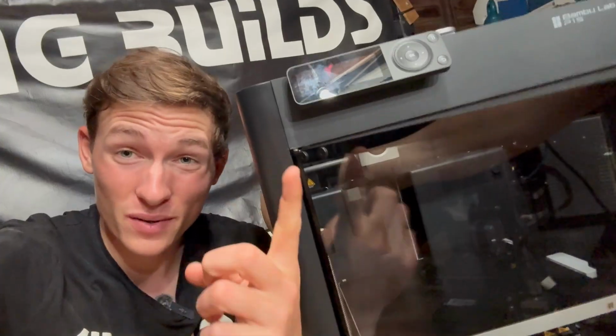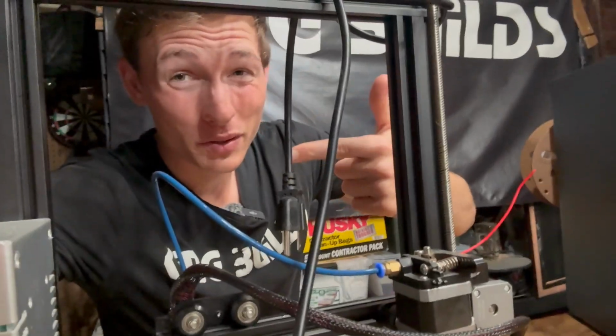Now, there's different ways your 3D print can fail. For example, if the bed isn't level, the first layer won't be good. If the first layer is messed up, the whole 3D print usually won't work well. The BambuLab, this printer right here, has auto bed leveling. Now, the old 3D printer, this one you have to level by hand.